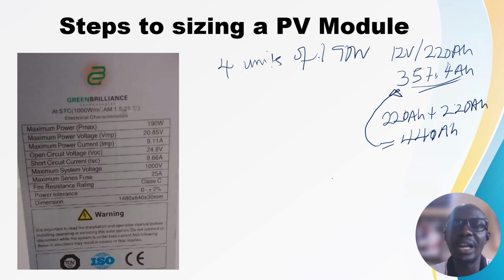You can connect your panels in parallel and series, and intelligently the MPPT will do justice to any of the connections, but you can't do that on PWM. Apart from that, the PWM is not efficient, it wastes energy. But the MPPT will track the maximum power you need to charge your system.